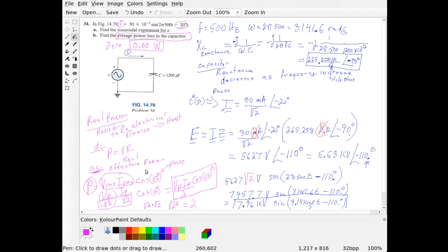So that's where that comes from. But you have to pay attention to this angle of the voltage and the current. But inside a capacitor, as we discussed before, capacitors store electrical energy inside of an electric field, and as they're charging, they're storing that energy, and then when you flip the current away and drive it in the opposite direction, they dump that energy back into the circuit.